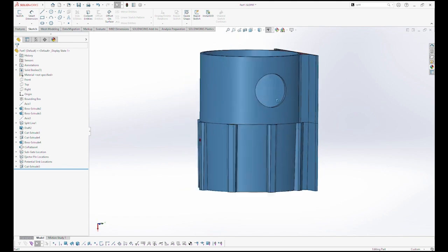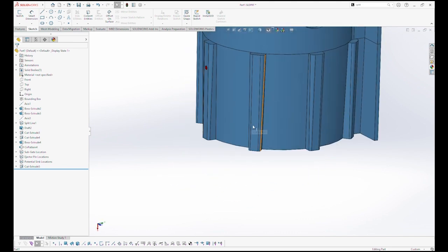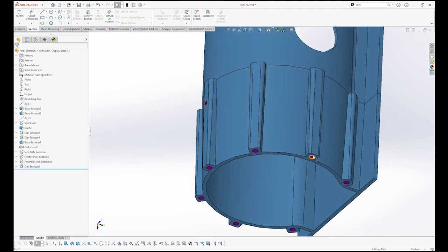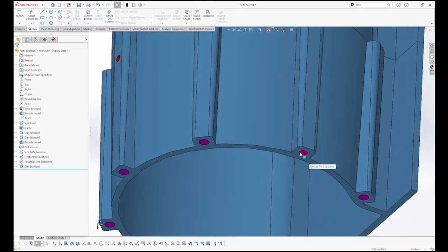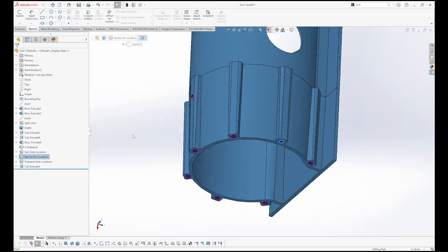So whichever resin you're using, you want to try to minimize that as much as possible. So I try to keep this feature as small as possible, and that's the smallest diameter pin that we can do. But in general, if your part will allow a larger ejector pin than 15 thousandths, the larger the better, whatever the geometry would allow as it relates to ejector pins.